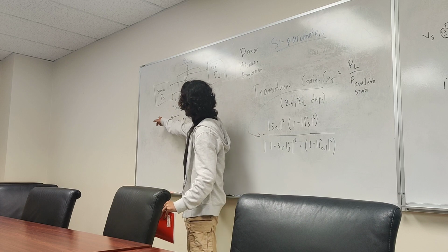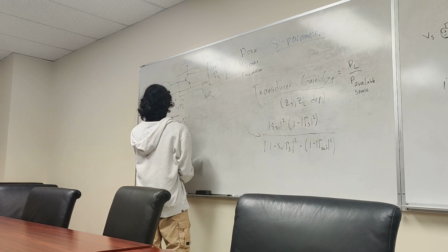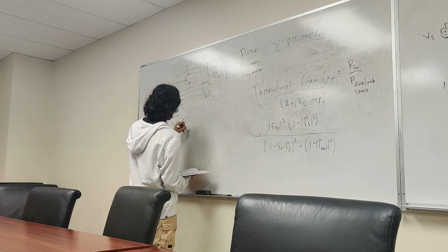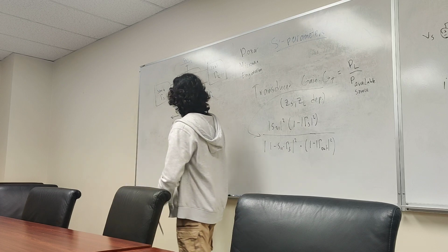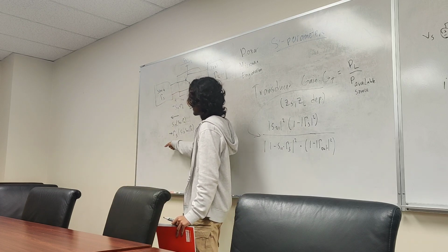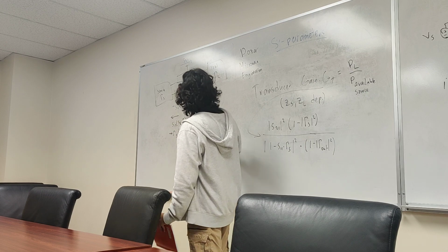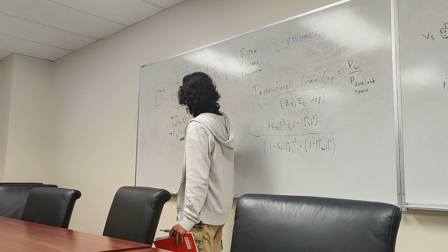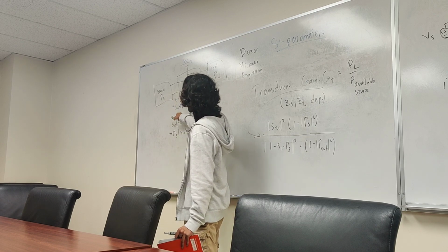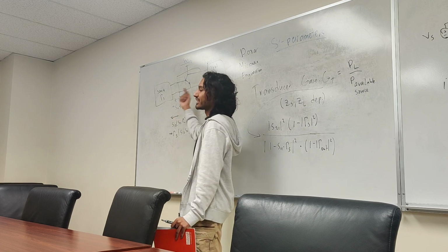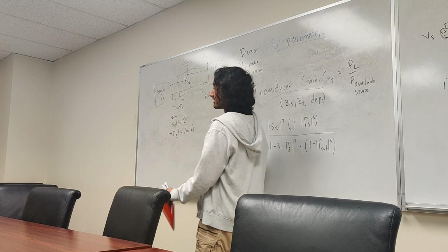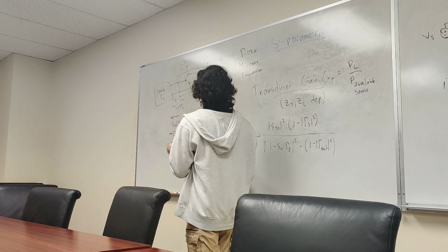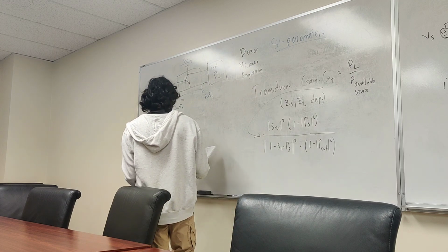Now this is going to hit the source and reflect back. And what's going to happen now is S12, S21, gamma L. I'm trying to use parentheses to establish the fact that this is already present and this is the new thing. So now we see over here we get gamma S, S12, S21, gamma L going back into our device, the S11 gamma S from before. And this whole cycle repeats over and over and over, infinitely. Are we good with that? Any questions? So, what we can do is keep writing out these terms.